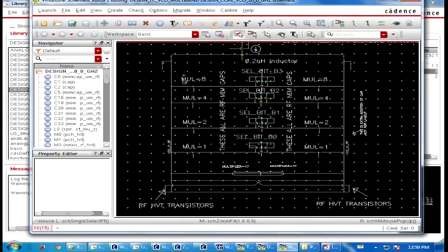These are the capacitors which will vary your frequency. These are the switches. This is a cross coupled transistor, and this is a varicap, MOS varactor. So these are the components in the VCO: cross coupled transistors, varicap, switching transistors with capacitor, inductor, plus 2 biasing transistors.